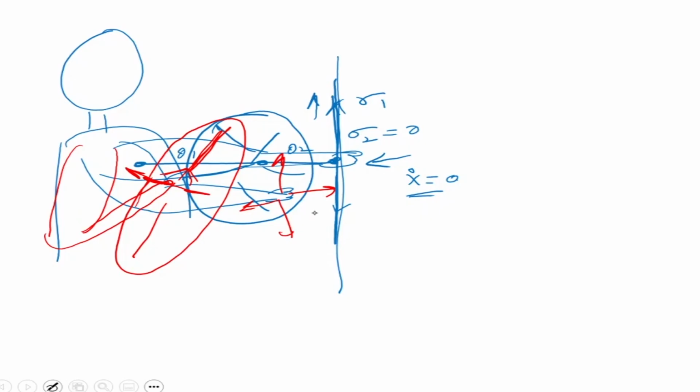The Jacobian is a very, very important matrix, and it is used to determine not only the singular positions, but also concepts of energy consumption and the directions in space in which you can move. If you're trying to move in a particular direction very quickly, you have to find the ellipsoid in that position and then see where the directions of sigma 1 and sigma 2 are.